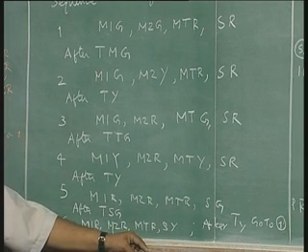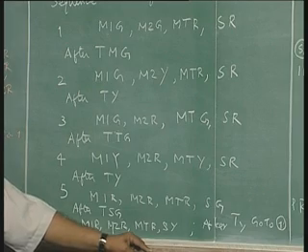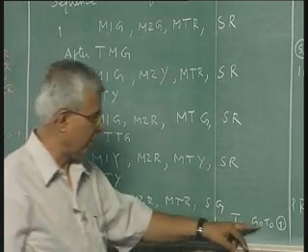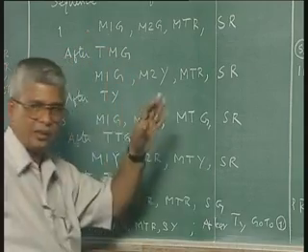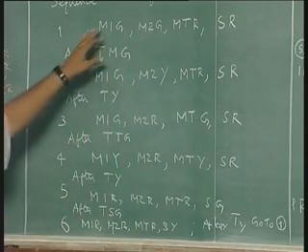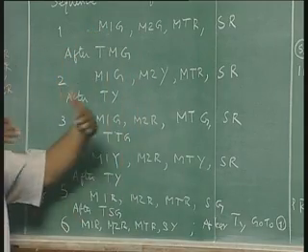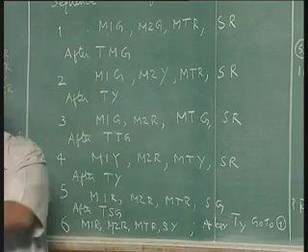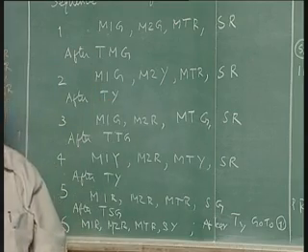Ty stands for the yellow light period, in this case from side to main. So, after Ty we go back to 1, which is our first primary state, main 1 green and main 2 green, both directions traffic, no turning on this side, no turning on this side.